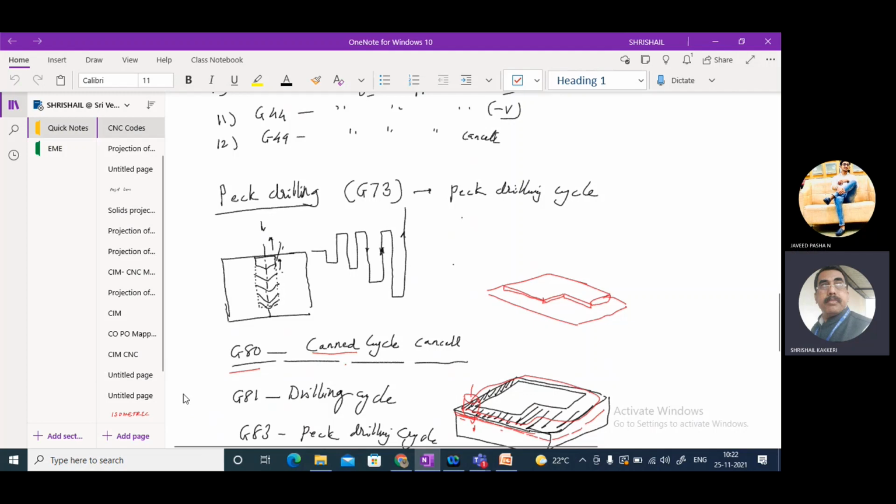And in case of the CNC machine cutting tools, is there any cooling system in the drilling machines? In the flute itself, there will be a coolant circulation method. Coolant will be circulated within this one. In normal drilling, what we are going to do, we are going to pour the coolant. But in the flute, there will be a spiral shape, and small holes will be provided. Through this, the coolant will be circulated. So these tools will be very costly. You understood? These will be costlier.